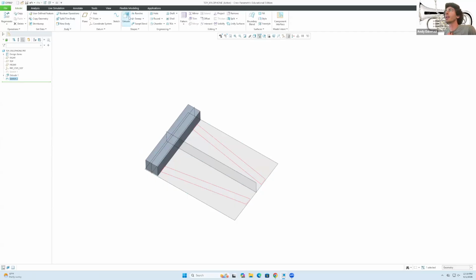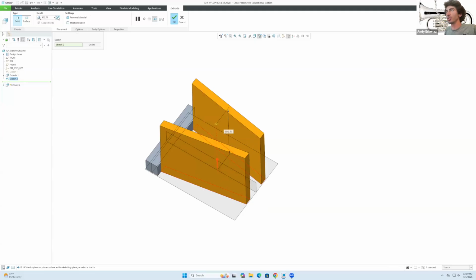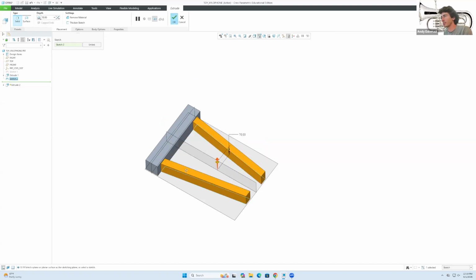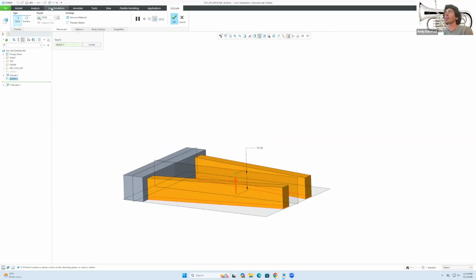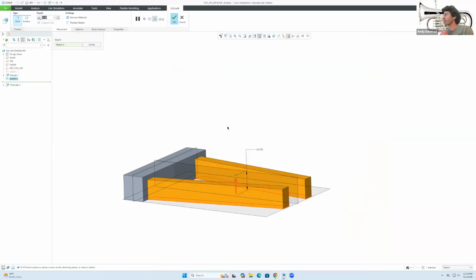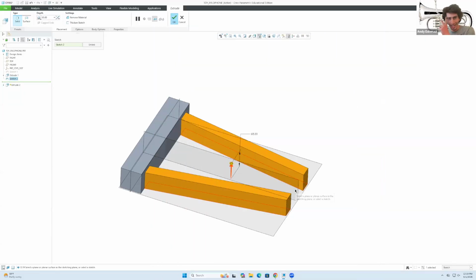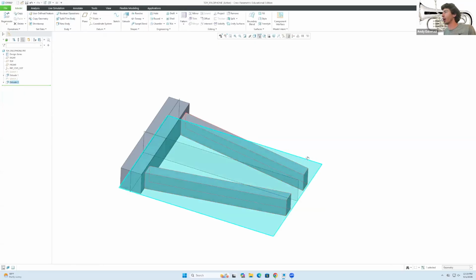We click on OK, and now we go to our friend the extrusion, and it automatically detects these areas. So we can obviously change the height. So if we made the previous one 80, we could possibly make this 70. Maybe that's maybe 65. Let's see. Yeah, I think that should definitely work. So we have all of those pieces in here. That seems mostly all right. It's going to be sitting in there. And then we're going to obviously add like a little beam in there just to make sure that things are fine. So I'm going to click on okay.